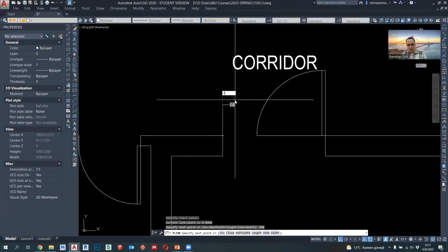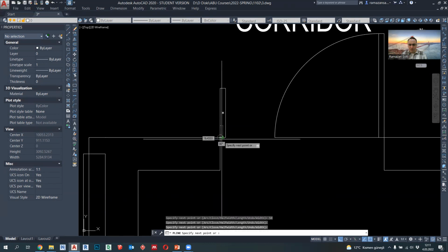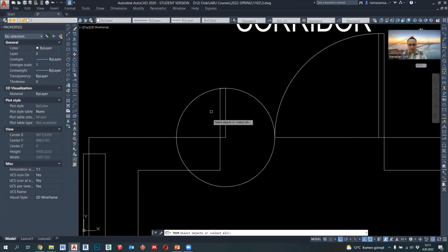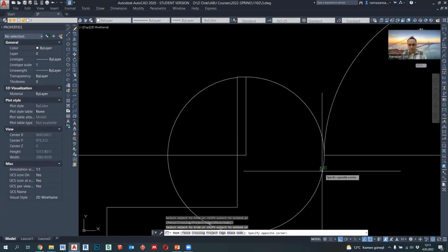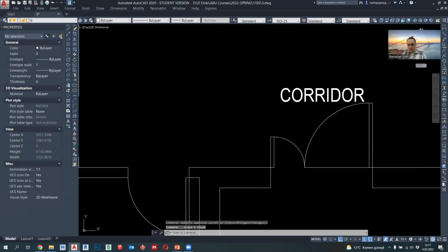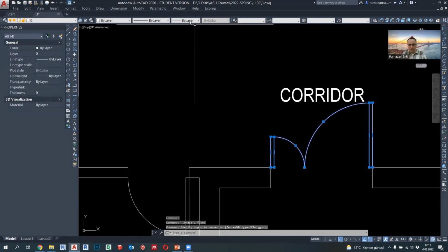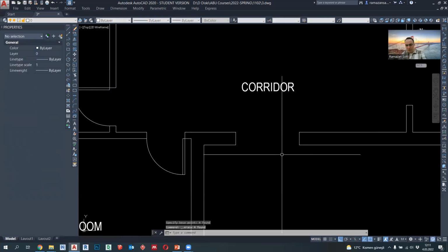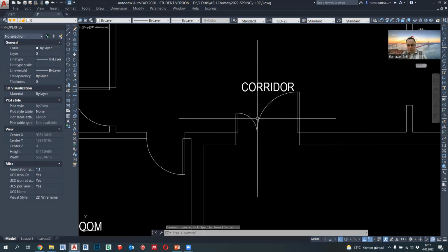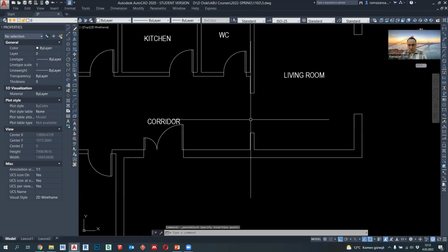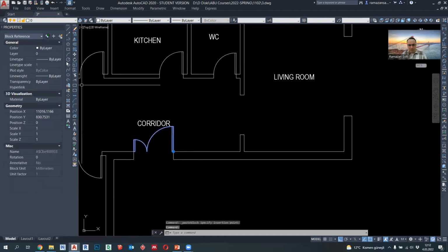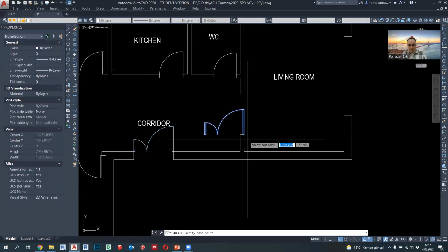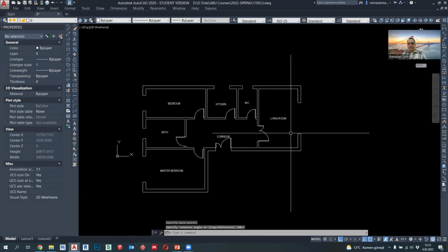So the door wing will be 45 centimeters. And let's assign the line thicknesses again for these doors, double door. And let's copy the same door at here also, having same length. Okay.